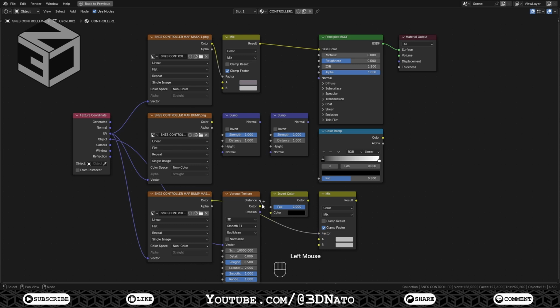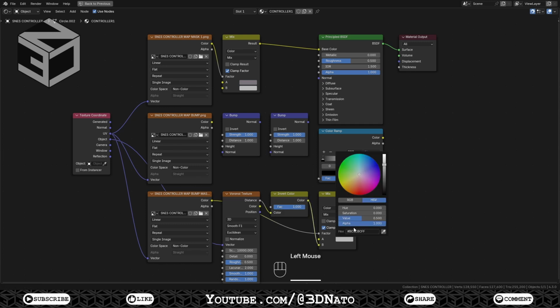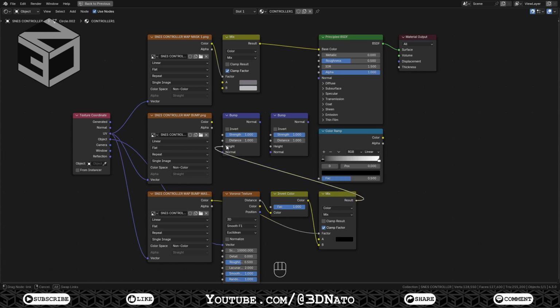Connect the Voronoi texture distance to the invert color. This will create a negative of the Voronoi. Connect the invert color to the mix color B and set color A to black. Connect the mix color result to the first bump height and set strength to 0.1. This will make some parts of the controller have a plastic texture from color B and some parts be smooth from color A.